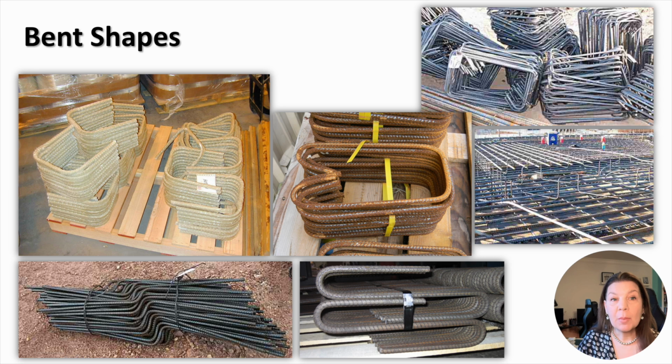The location, mark, type, size, length and number, and bending details of each bar or fabric in a reinforcement drawing of a structure is described in a comprehensive list. This process of listing the location, type and size, number of, and all other details is called scheduling. In the context of reinforcing bars, it's called bar scheduling. In short, the bar bending schedule is a way of organizing rebars for each structural unit, giving detailed reinforcement requirements.